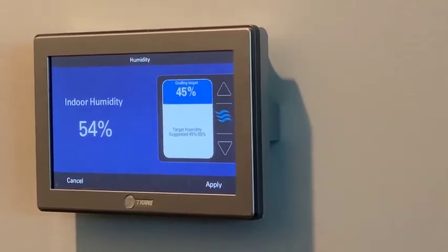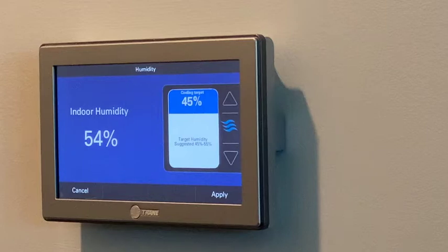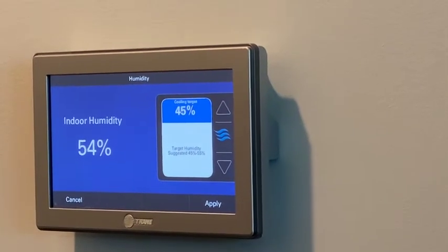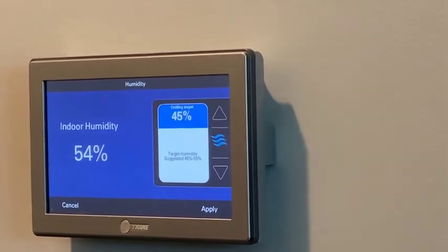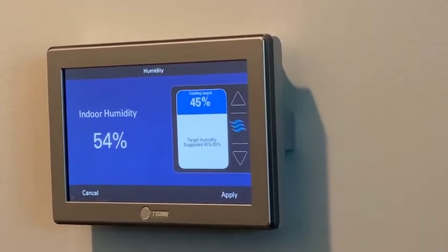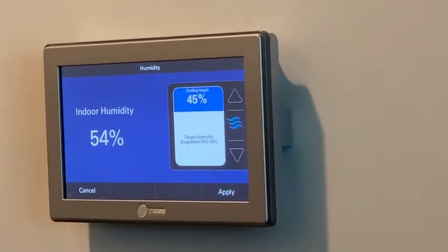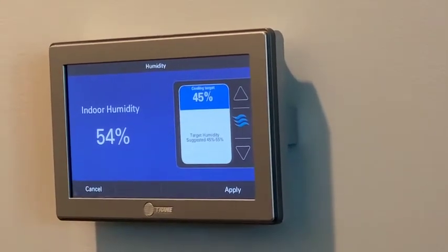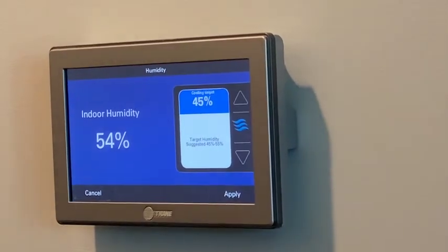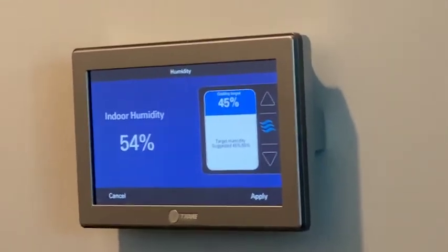So I hear people say, always keep the fan on, or don't always keep the fan on. What's the rule of thumb? Fan should always be on auto. And are you good with the fireplace in the winter going on and getting the house nice and warm and putting the fan on? In the winter time, if they want to run the fan in on or circulation mode, they can, but only in the winter. You would not want to do that in the summer.